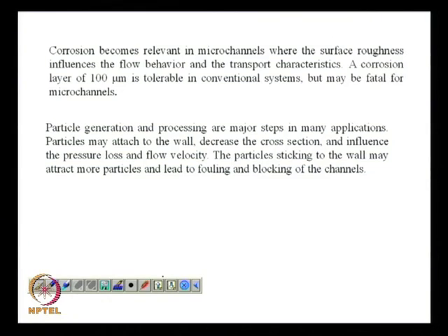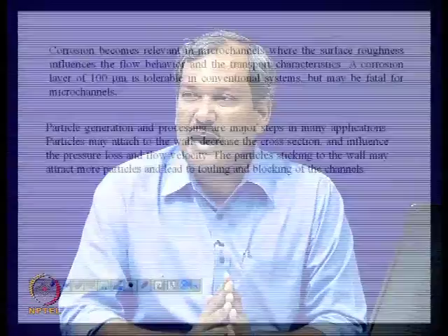And there are situations in which a particle may stick to the wall, and once they stick to the wall, they act as the nucleation site, and they attract more particles, and they create a colony of particles around it, thereby increasing the value of epsilon, and thereby diminishing the value of dH even more. And the moment the value of dH diminishes, the value of delta P is proportional to 1 by dH to the power 4. So, if you keep everything else the same, even a very small change in dH can give rise to a manifold increase in delta P.